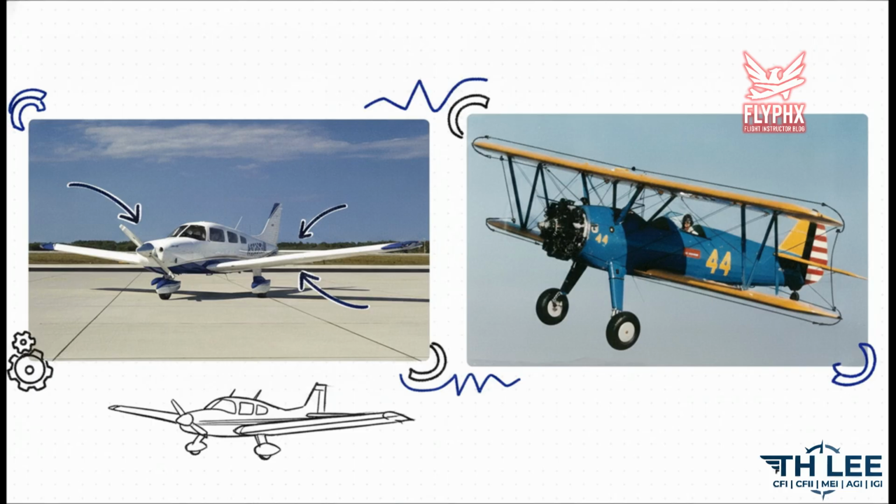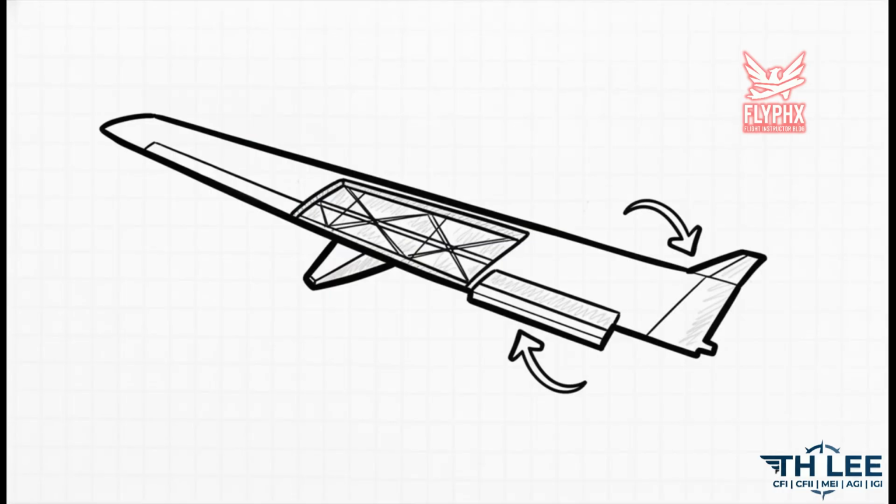And just as a side note, some modern low-wing aircraft use a full cantilever wing, which is engineered completely without external struts, carrying all those massive structural loads internally. So what exactly is inside those wings carrying all that load? Well, underneath the thin aluminum or composite skin, you've got these robust structural spars running lengthwise, along with ribs that give the wing its exact aerodynamic shape and thickness. Plus, these spaces often house your fuel in integral tanks or flexible bladders.